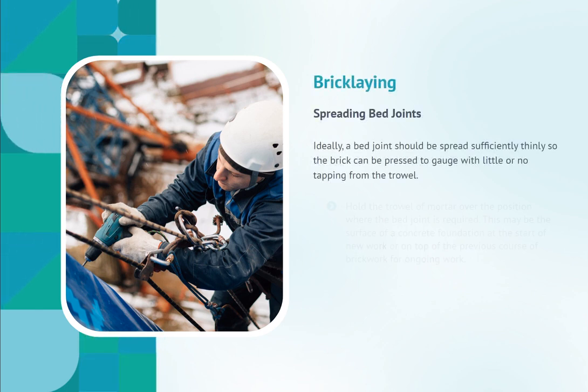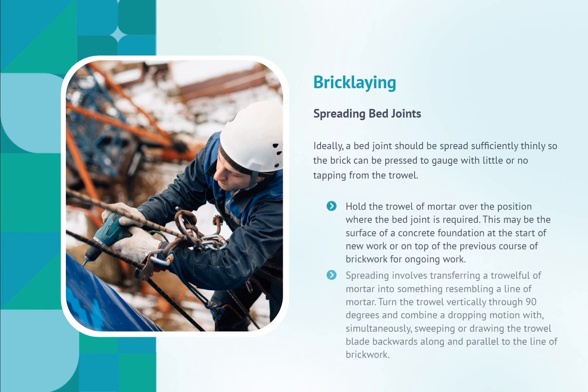Spreading bed joints. Ideally, a bed joint should be spread sufficiently thinly so the brick can be pressed to gauge with little or no tapping from the trowel. Hold the trowel of mortar over the position where the bed joint is required. This may be the surface of a concrete foundation at the start of new work or on top of the previous course of brickwork for ongoing work.